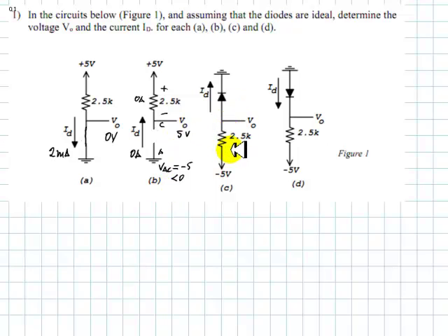The next question, this one. Let's see. This voltage down here is -5, the one up here is 0. If possible, the current would flow from 0 to -5, downhill like this. The diode will impede that. I'm going to assume the diode is open, but we have to prove it. If this is open, the current is going to be 0 amps. But if that is indeed open, then VA is less than VC. Well, let's see what is VA.